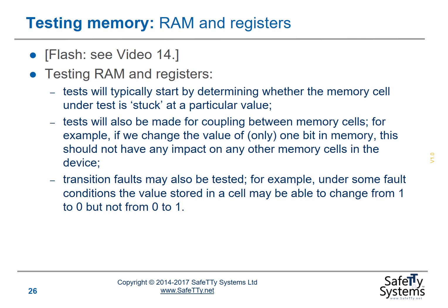In terms of testing flash memory, we'll discuss this in the next video. In terms of testing RAM and registers, the tests will typically start by determining whether the memory cell under test is stuck at a particular value. Tests will also be made for coupling between memory cells. For example, if we change the value of only one bit in memory, this should not have any impact on any other memory cells in the device.